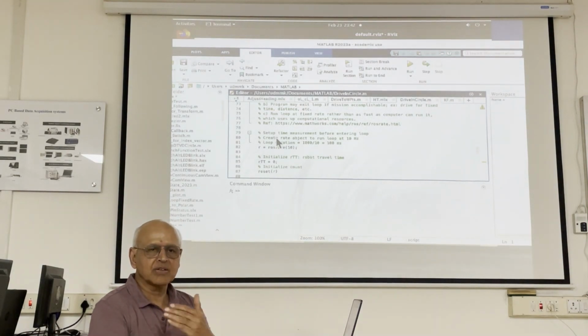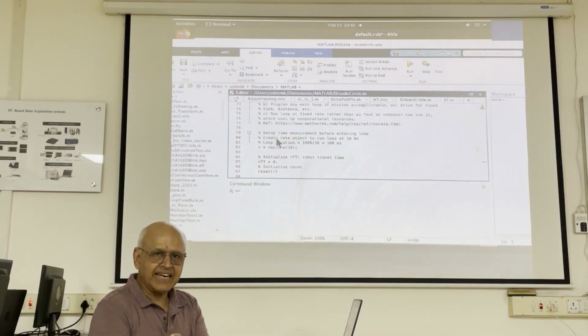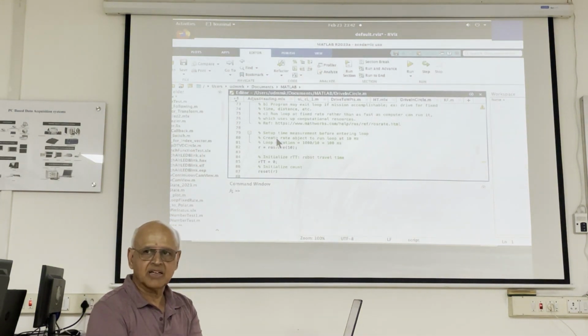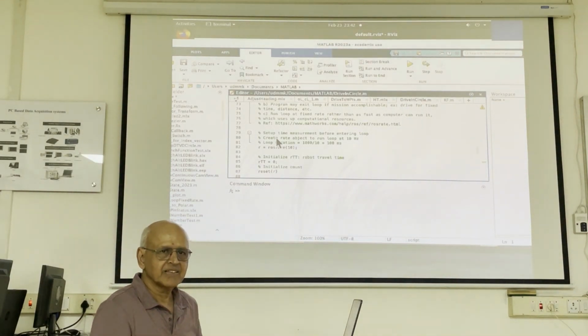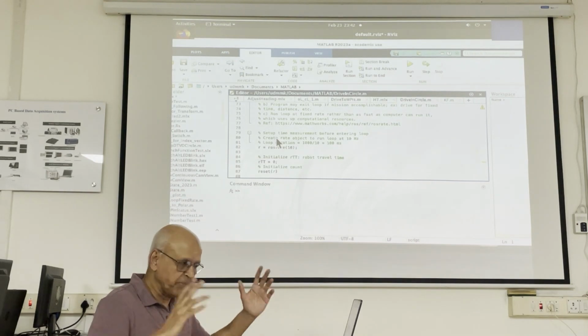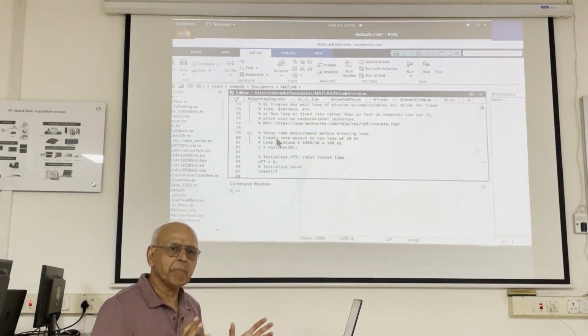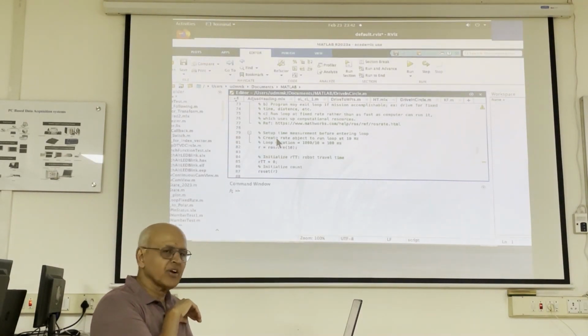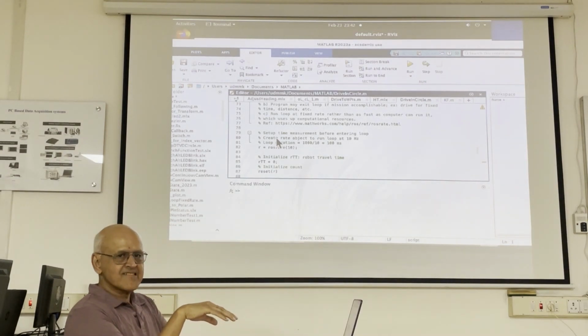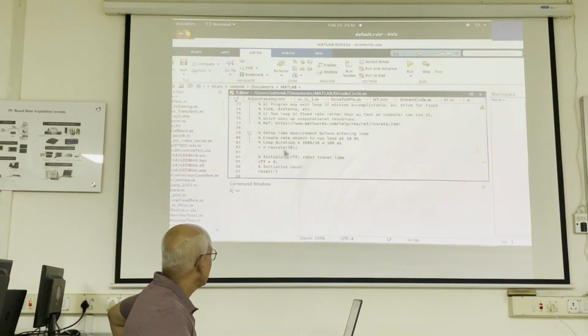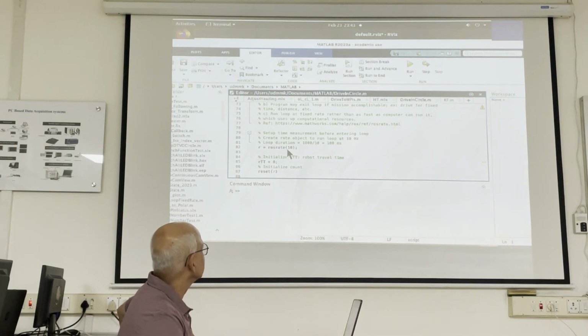So if you slow down the loop rate, then it is possible to take that computer time and use it on other nodes. Remember, we have a number of nodes running in ROS, typically, not here. Typically we have a number of nodes running, multiple robots. So we don't want to run each loop the fastest you can based on your computer speed. Particularly when you have a slow computer, you don't want to do that. So this is an attempt, the ROS rate. So here's the reference if you want to go look it up.